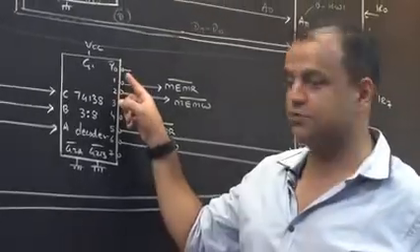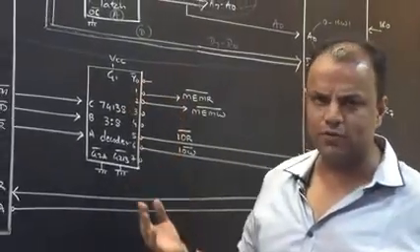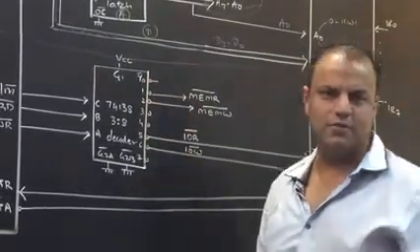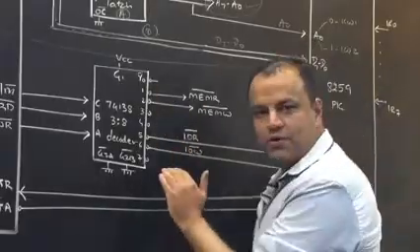That's why we show the bar, that's why we show the bubble. You may show only one of them, that also means the same. You may show both, it doesn't matter. It's just the way of drawing it. So all outputs of the decoder are active low.